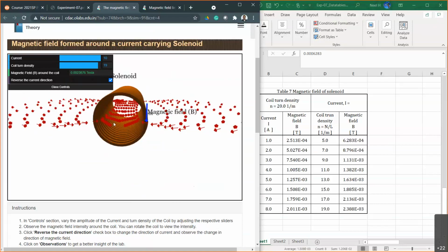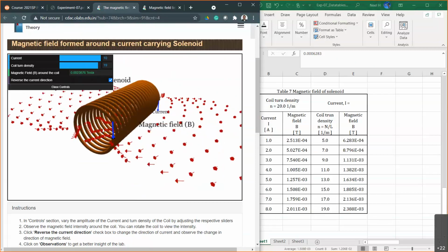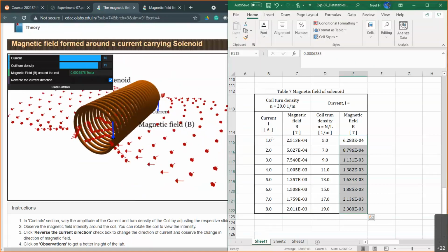Yeah, anything, depending on the type of alloy. Most of the alloys in a belt and things like that are aluminum-based alloys. Aluminum is non-magnetic, so generally not a problem. But any metal that can be magnetized by an external magnetic field, like steel or any iron particles in there, can actually interfere. Okay. All right, so let's take a look at this same thing.